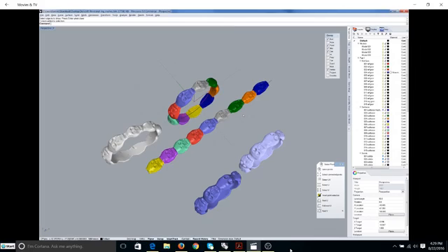Correct. Remember that this technology is what's called line of sight, as is laser scanning. So if there's a deep pocket or an undercut and it can't see it, it's not going to capture the data. But once you capture it, you can process it through EasyScan. Again, you can fix holes, and you can decimate things to make the files smaller. Obviously, some programs are going to have memory issues, and you want to make sure the scans can be manipulated without slowing your system down.